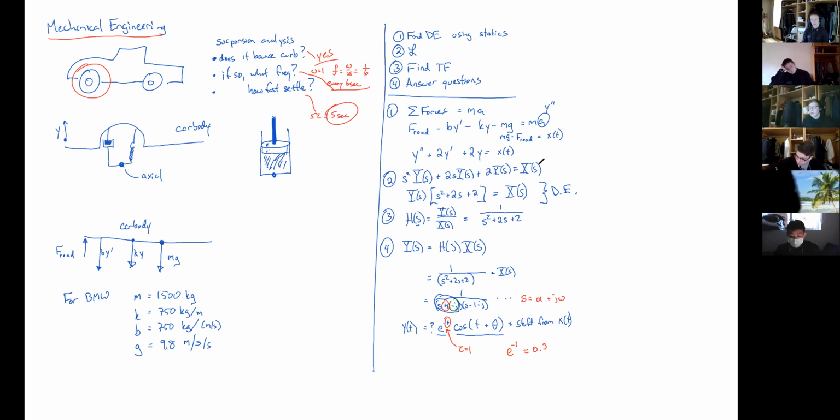To find that answer, you would take a look at your original equation. What would happen on the moon is your g would just be a different constant, so your x would just be a different constant. Does that change your H? Nope, your system transfer function is independent of your input. So your H doesn't change, so none of your analyses change. You can confidently lean back in your chair and say, nope, on the moon it'll still oscillate if it goes over a rock, and it'll still oscillate once every 6 seconds and dampen in about 5.